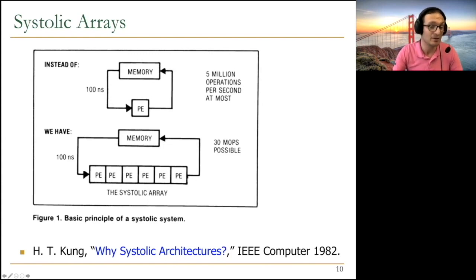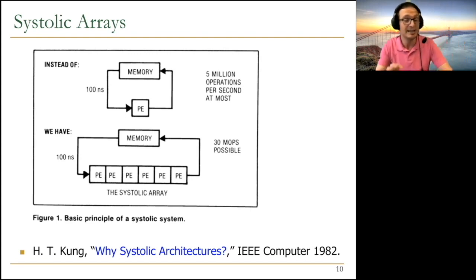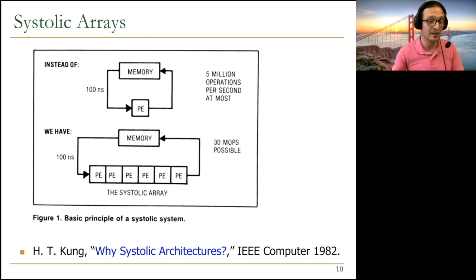And this is one example of a systolic array. You basically have 6 processing elements. But as we will see, systolic arrays can be 2-dimensional as well, or not so regular as well. They may have different diagonals as well. We will see some examples of this. So linear is, of course, the simplest example, right? And the connections can be multidimensional and not as regular as we see over here. Basically, this processing element may be back connected to this processing element also. So we will also see the differences from pipelining soon.